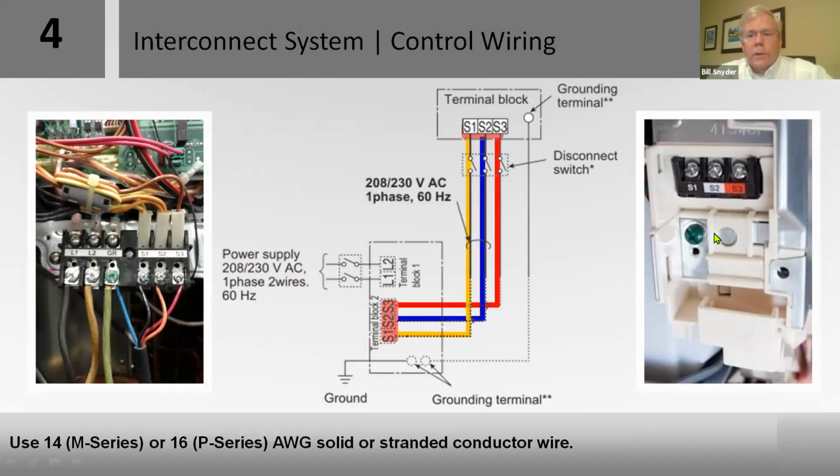Now here is what the indoor unit looks like, S1, S2, S3. There's a channel that you can push this wire in. It pops up here and connects here. Use the appropriate size wire. Some of our units use 14/3 with a ground. Some use 16/3 with a ground. So make sure you use the proper sizes.